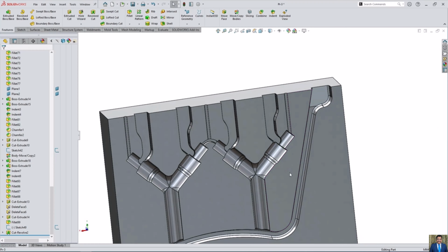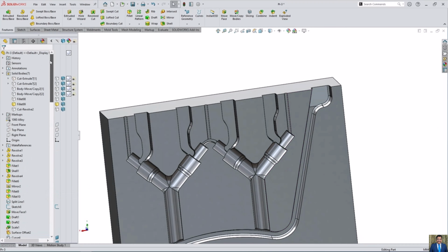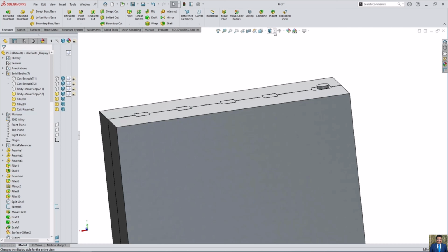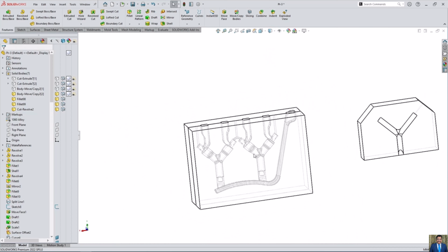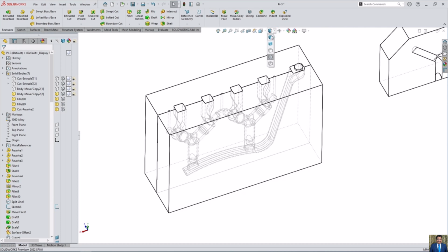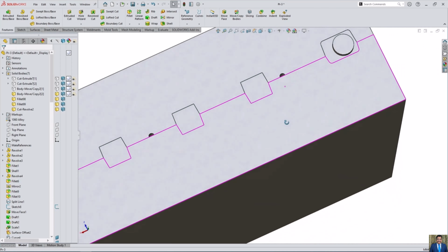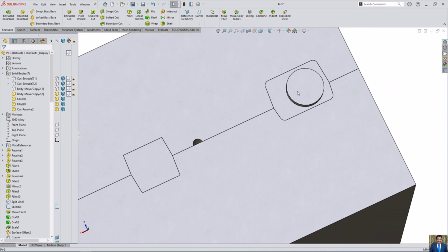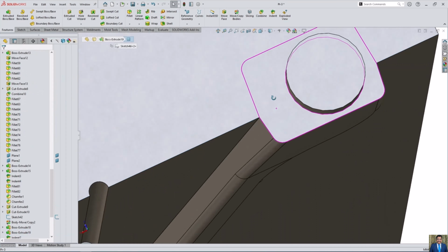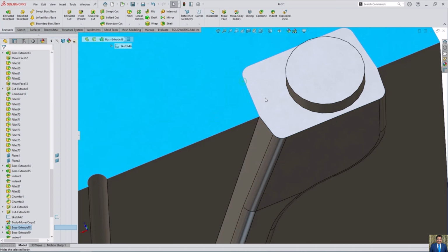Now it is not complete, but we are close to finishing our project, and also we need to have the injector pin, the liner, but I want to show in which area we want to have the injector pin, and also the liner should be here and here, and the injector plate. But before we start, it's better we control on which side we want the piece to stick, and also the pan geometry, because we see here that we have changed the draft a little in this part. I want to show.